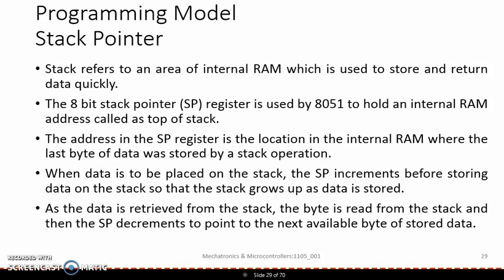Stack refers to the area of an internal RAM which is used to store and return data quickly. It is an 8-bit register which is used by 8051 to hold an internal RAM address called the top of the stack. The address in the stack pointer register is the location in the internal RAM where the last byte of data was stored due to a stack operation.